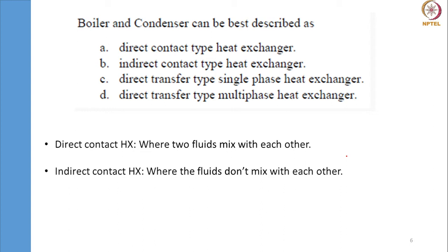In that case, both fluids are not mixed together, but based on the evaporation rate, our tube side fluid can be 5% vapor, maybe even 40% vapor, and the inlet shell side steam is in the vapor phase, and that can be collected as a condensate.